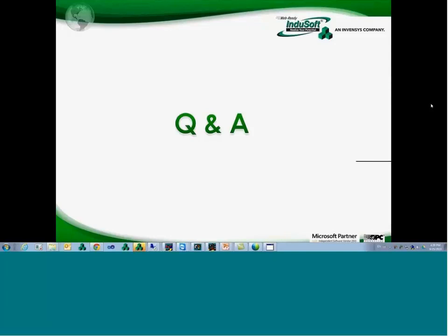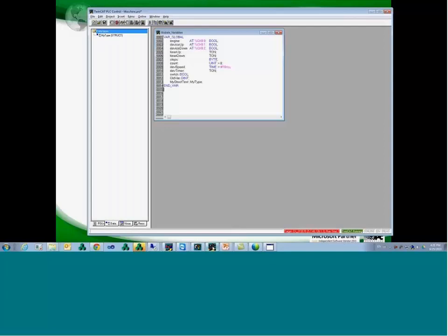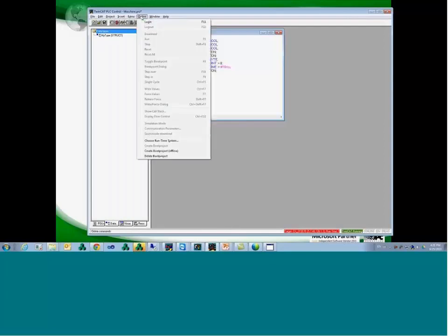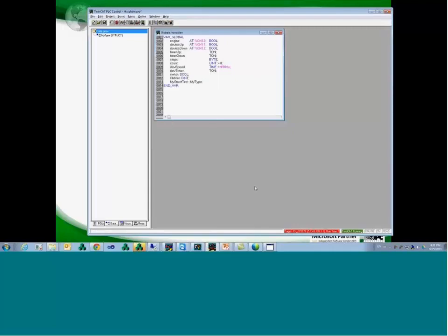So let's say that you have a touchscreen panel for a machine. You're going to communicate with a couple hundred tags. Yeah, I would use the tag integration. You know, it's very simple. I'm going to always have the TPY file updated because it gets updated automatically. I'm going to give an example here. So I'm going to go and create a new variable here on my TwinCAT.